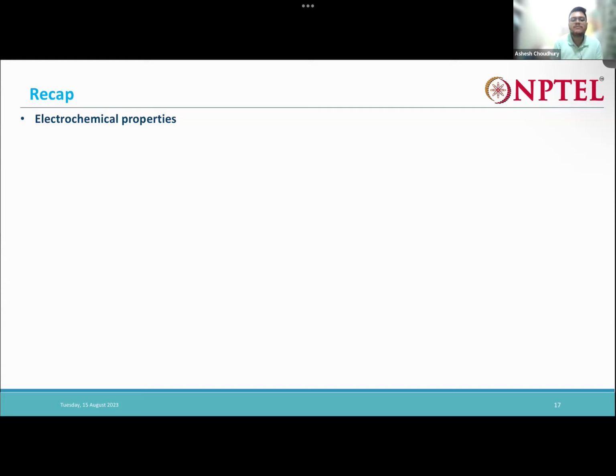And when we use polymeric reinforcement, meaning any kind of geosynthetic, say geogrid or geotextile, whatever you use, in that case, you need to consider that the soil pH is within the range, and also the plasticity index of the soil is within the range. That's all. So the criteria is more stringent when you're using the steel reinforcement.